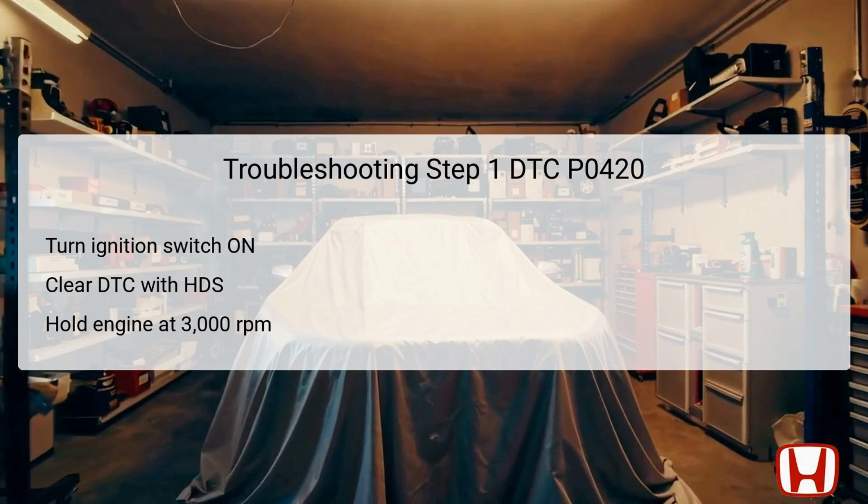Once the DTCs are cleared, the engine should be started, and the technician must hold the engine speed at approximately 3,000 revolutions per minute, RPM, without any load, which means that the automatic transmission should be in park or neutral position. This step is crucial, as it allows the catalyst to reach a certain temperature, and the vehicle's radiator fan should activate during this process, indicating that the system is adjusting properly to the engine's operational conditions.